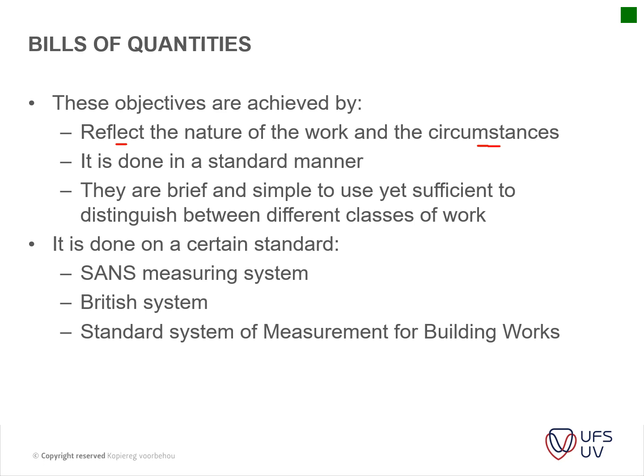It's very important, if you think about it, that if you leave that for assumption and you have 6 different contractors tendering on a project, and you assume that there's no hard rock and another contractor comes in and allows a certain percentage for hard rock, then it will be difficult to evaluate the tenders and get the right comparison, because one included this and the other excluded this, so it becomes difficult to evaluate the tenders.